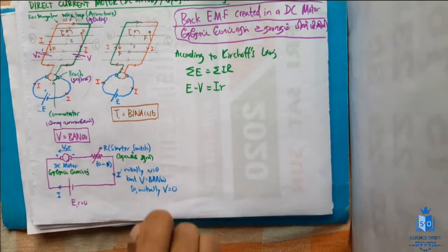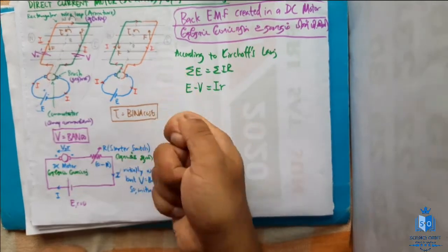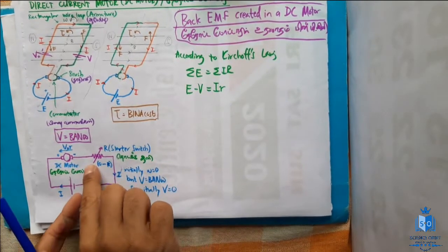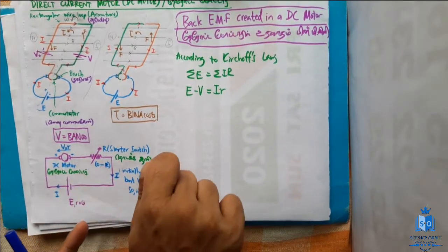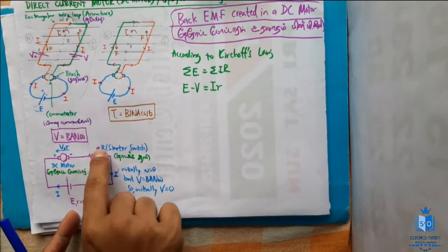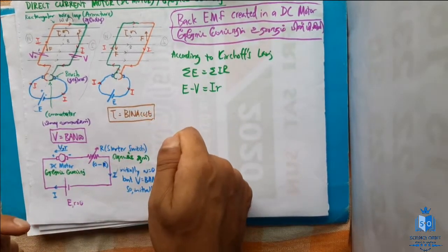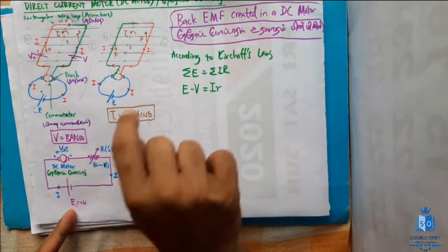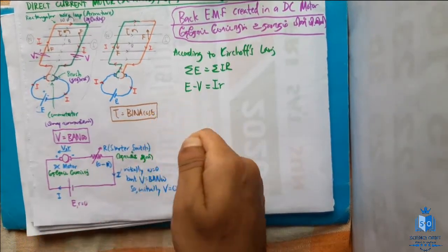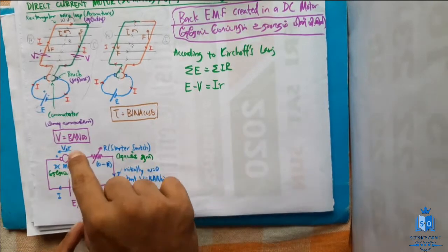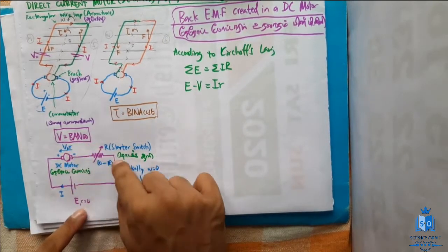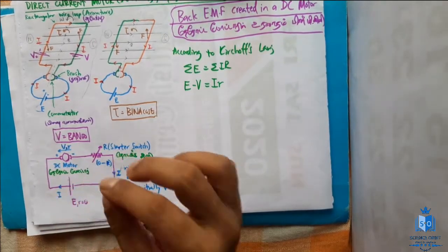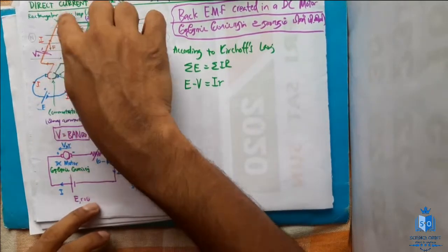So when you put the key and turn the key like this, there is a spring. What it does is turn this resistance from 0 to R. Now when you do this, it will get started. At that point this resistor is there, and here you make the resistance capital R by turning the key. So the initial resistance of the circuit is simple R and capital R. So a larger resistance is there. Hence the initial current will be small, so that this will not burn.